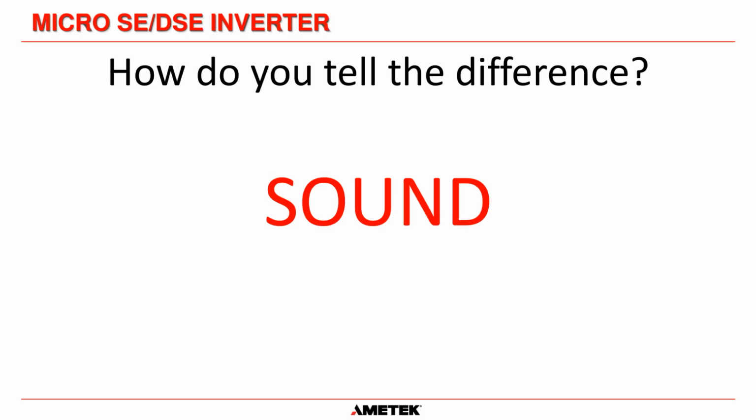It's low frequency, and it's quite distinct, and it's quite loud in some cases, compared to a PWM system, which switches at 8 kilohertz. So the frequency that you hear is an 8 kilohertz whine. It's kind of like an ee sound. So the sound is very, very different between the two technologies. Okay.